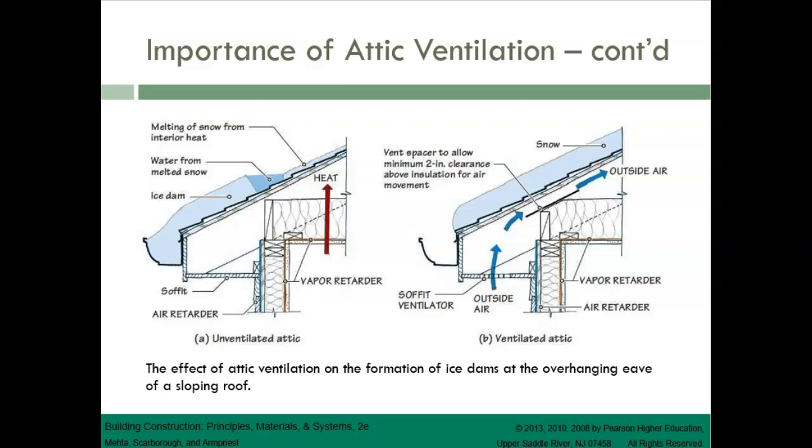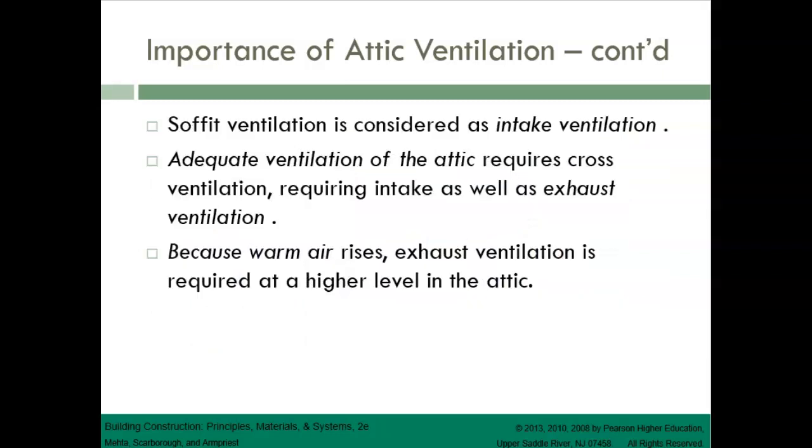If the attic is not ventilated, it remains relatively warm because of entry of heat into the attic from the warm interior, but the eave overhangs are cold. This melts the snow in the middle of the roof, which freezes again at the eaves, forming ice dams. The problem is worse in a roof ceiling assembly with inadequate insulation.